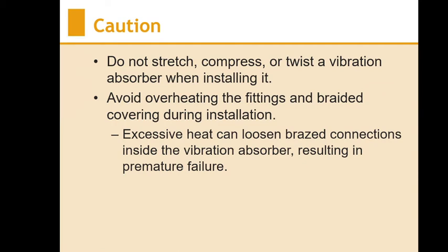Caution about these: do not stretch, compress, or twist vibration absorbers when installing them. Avoid overheating the fittings and braided coverings during installation or brazing the ends. Excessive heat can loosen brazed connections inside the vibration absorber, resulting in premature failure.